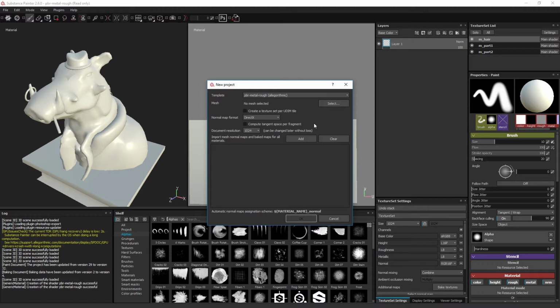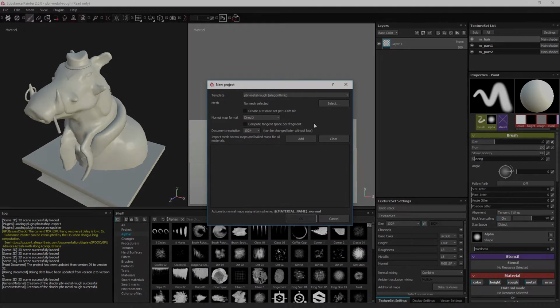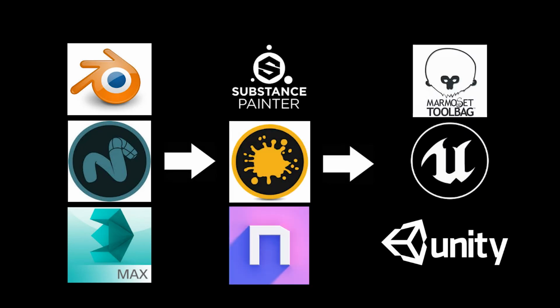If the modeling and texturing environment sets the vertex normal by three components, but the rendering environment sets the vertex normal by two, you get the same problem. To make sure your normal map is projected correctly, you need your modeling environment, texturing environment, and rendering environment to generate the vertex normal at the same angle, which means using the same method for setting the vector.